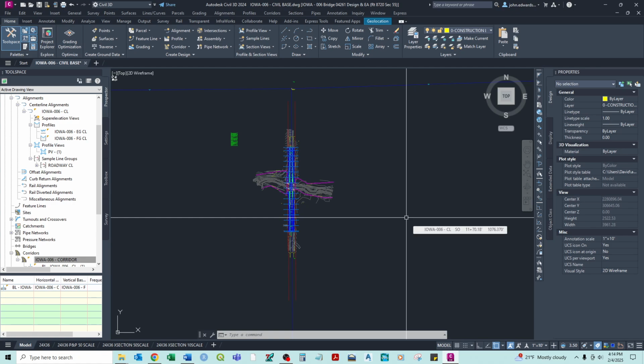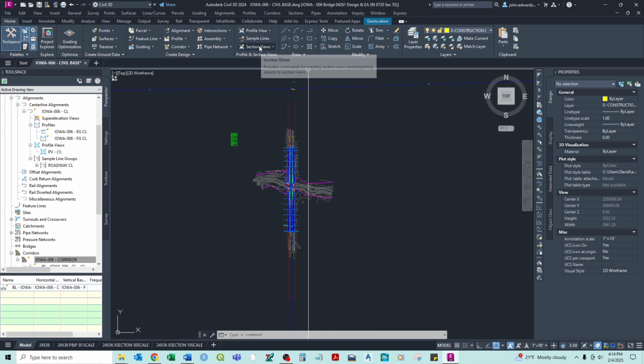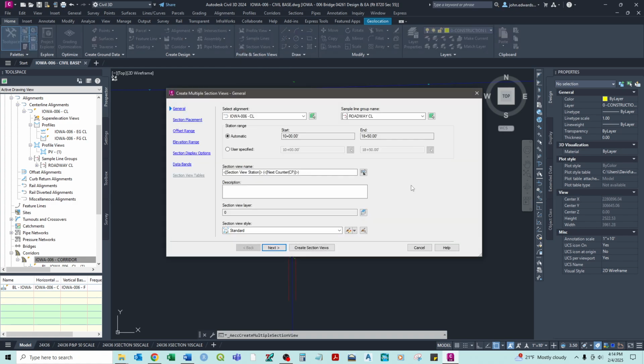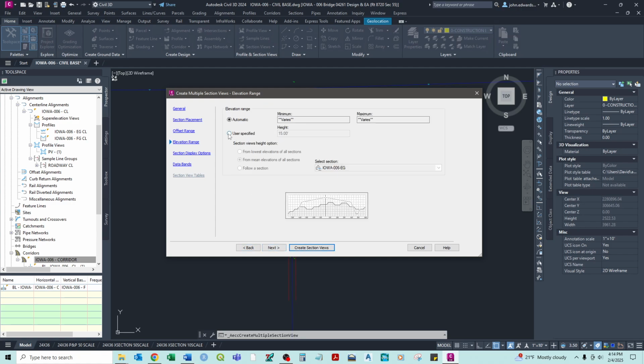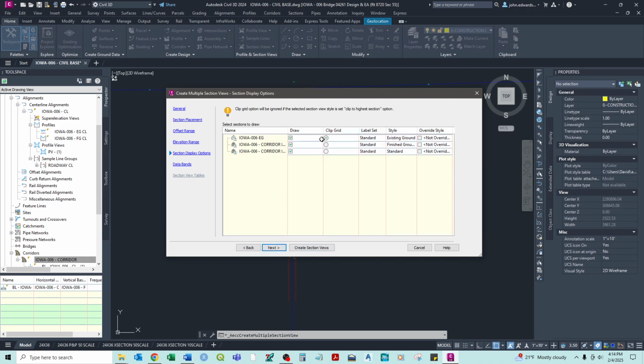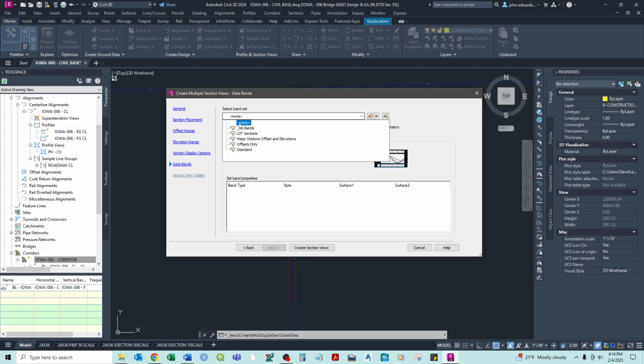Again, this is specific to our style, and when we set that drawing template, and I'll show you here in a second. So we'll go back to road section. Here, it's labeled cross section 10 scale, and that's why that messed up, because it was set to the wrong scale. I want to plot by page. That's okay. Follow a section. Draw. Turn all the labels off. Okay. Next, and turn the bands off. Okay.